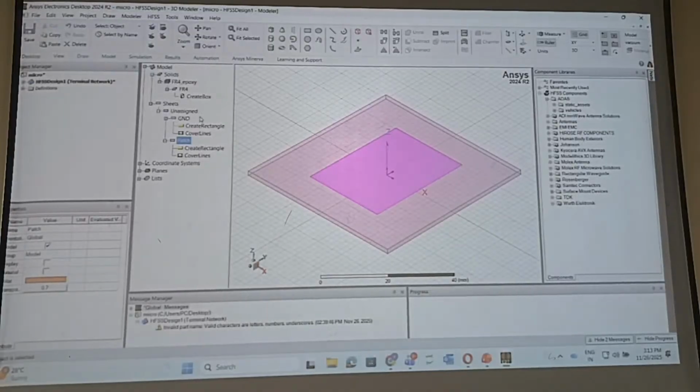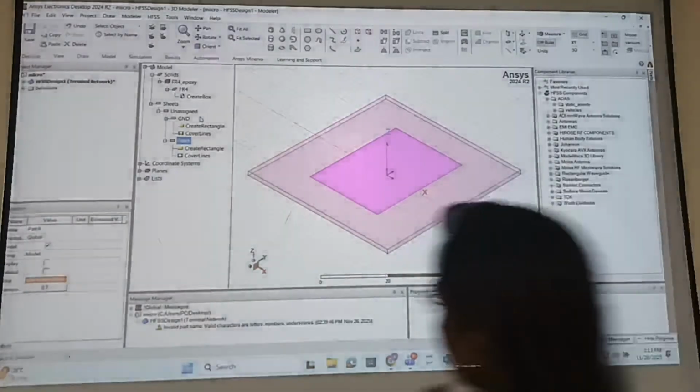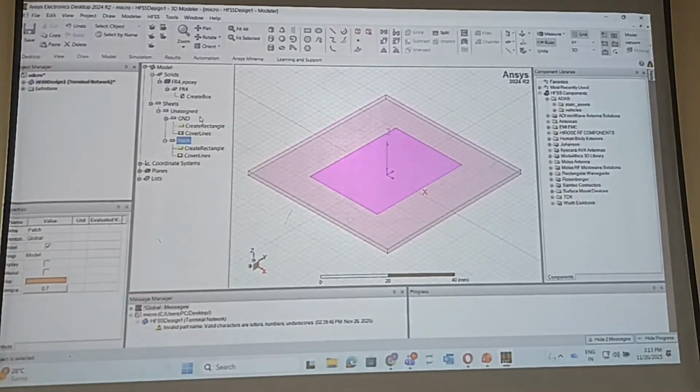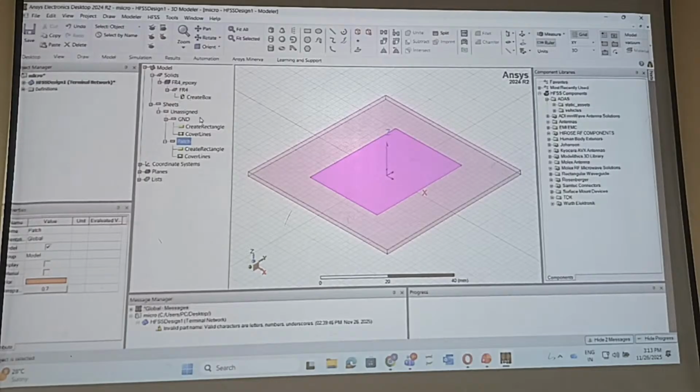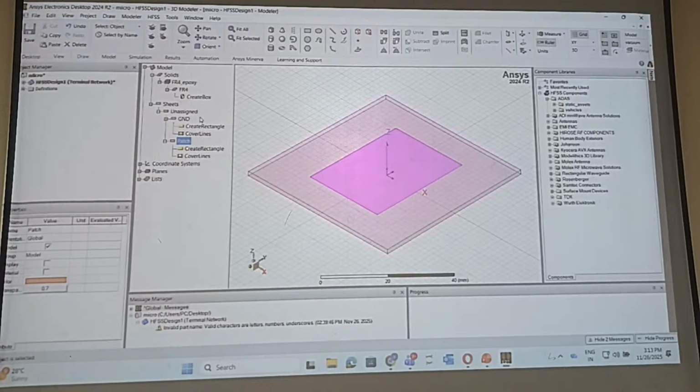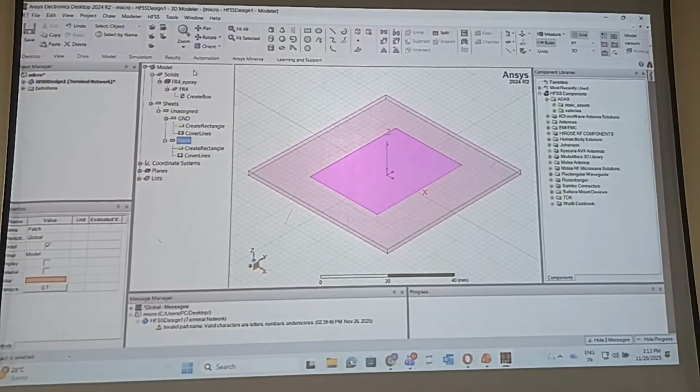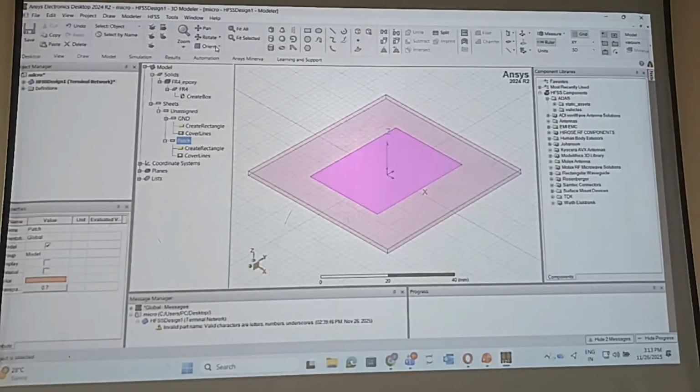I hope you have done these 3 steps. All of you done? So now we are going to create a microstrip patch line for 50 ohm. I'll tell you the exact length and width. We first will create this rectangle slot, and then we will apply a Boolean function so that the unwanted part of that patch can be removed.